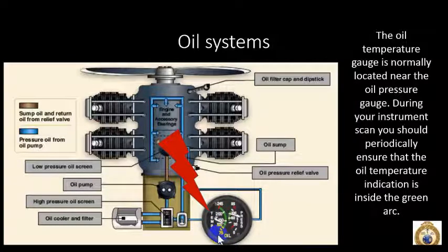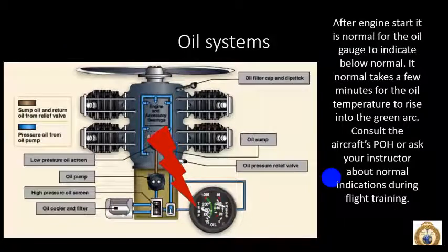Now, after engine start, you might notice that the oil temperature may be low for a little bit. After engine start, it takes a little bit for it to come up. But you don't want to be 15 minutes, half an hour, 45 minutes into a flight and not see that engine temperature come up. So keep that a part of your instrument scan. Your instructors will tell you how to do it.